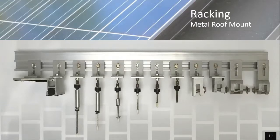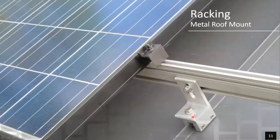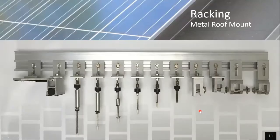If I was building a new house today or putting a new roof on, I would go with the standing seam. And if you look over here on the right side, you'll see these non-penetrating standing seam S5 clamps. These use pressure, as you can see in this image, to mount to a standing seam. Unfortunately, here in Nova Scotia, standing seam is not that popular.